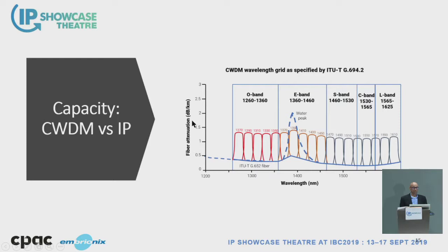As you all know, CWDM is wave division multiplexing, so effectively modulating individual wavelengths with individual independent signals and utilizing that in a system, but with some limitations. I often think of, I'm mentioning integrated routing here, but I mentioned in the past in the CWDM system, people would implement some control at the remote site, but they would modulate one of the wavelengths with just the RS-422 signal. So you're then modulating a wavelength of fiber that's capable of gigabits per second with a signal that's 38.4 kilobits per second, right? So not making good use of the available technology.